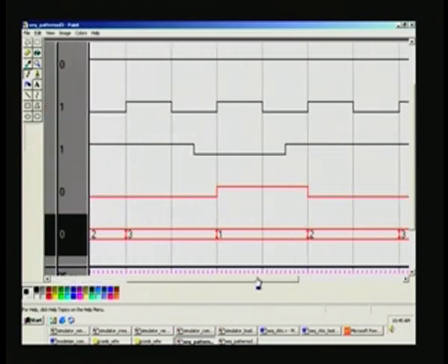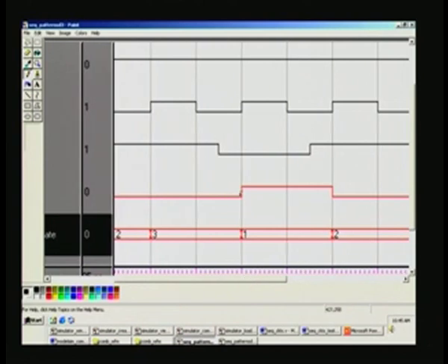So you can see now, we are in state 3. You can see once again it is taking place, all outputs take place only at the following clock edge, right, being a synchronous machine. If it is a Boolean expression, then it would have taken immediate effect, right. Being a sequential thing, it will always take place only at the positive edge of the clock.